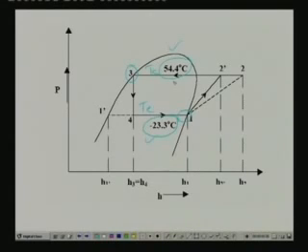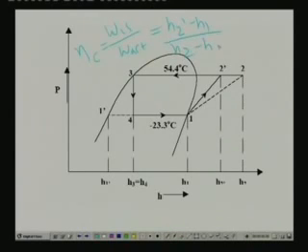So, this is the information given to us, and it is also mentioned that the isentropic efficiency of the compressor is 0.65. Okay. What do you mean by isentropic efficiency of the compressor 0.65? That means the actual compression process 1 to 2 is non-isentropic, whereas 1 to 2 dash is isentropic. And from the definition of isentropic efficiency of the compressor, you can write the isentropic efficiency as isentropic work input divided by the actual work input. So, from energy balance, this is nothing but H2 dash minus H1 divided by H2 minus H1. This is given to be 0.65.